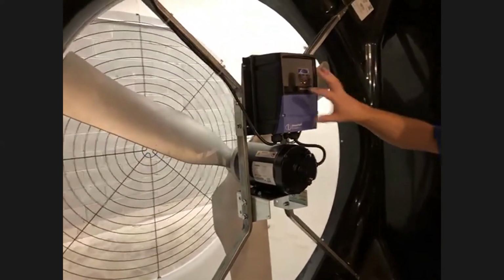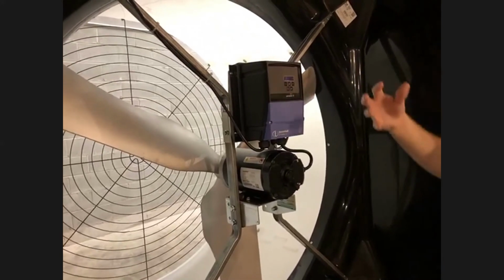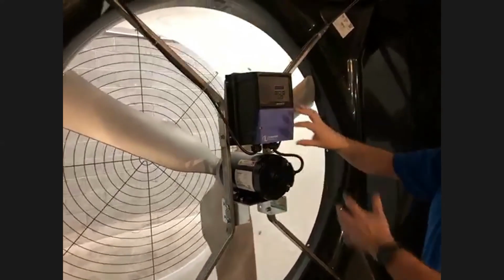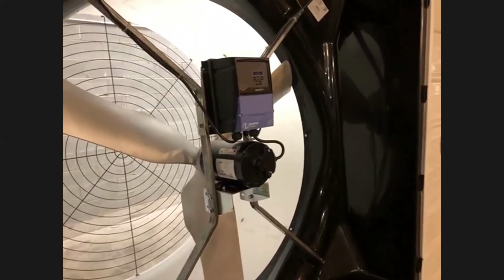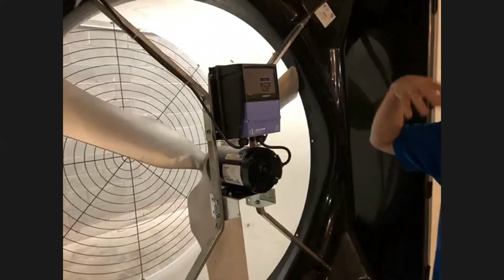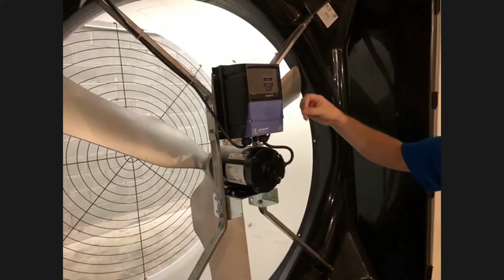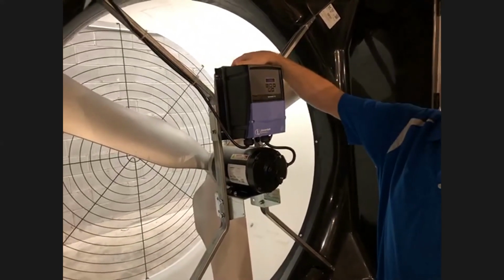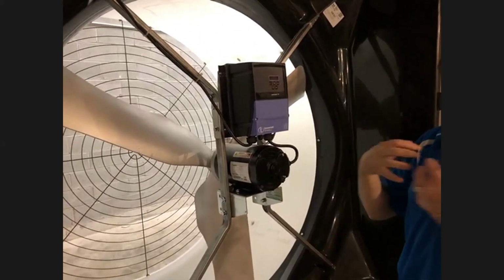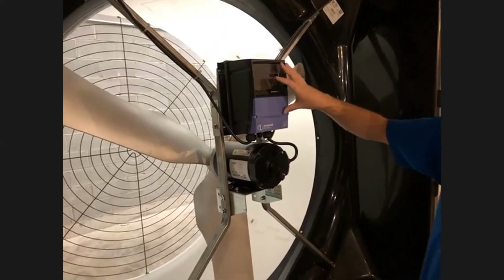With the location of this VFD, the variable frequency drive, as discussed earlier, people may like to put those on the sidewalls, but it's best right here because the airflow with the fan is keeping the drive cool. It's going to help prevent any issues that may occur if it's starting to overheat or anything like that. There are heat sink vanes in the back of it. Again, that keeps the dust off of them, which helps dissipate the heat from this. So it's a good location, good design to have this right here.